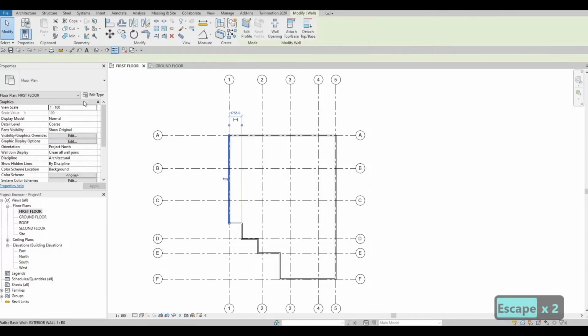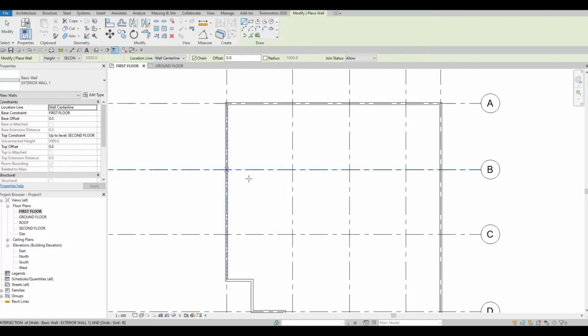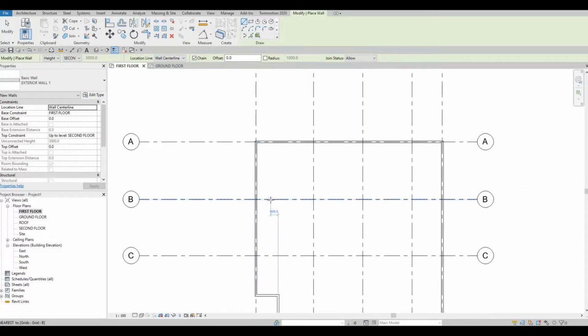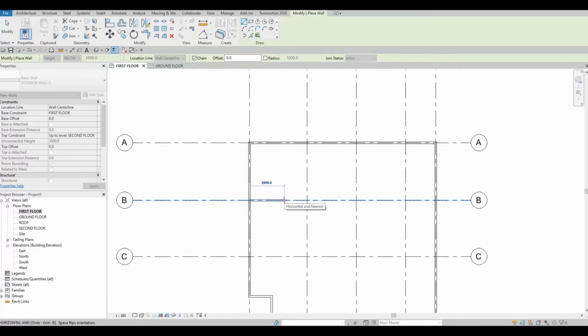So here, we're going to start. I'm going to select the exterior wall number 1, CS. That's Create Similar. It's under Modify. Basically, you'll be able to select one of the components that you already have in the view, and you'll be able to add it like this. So you can add it instantly. So now select B1 and add a wall that is spanning 1835.